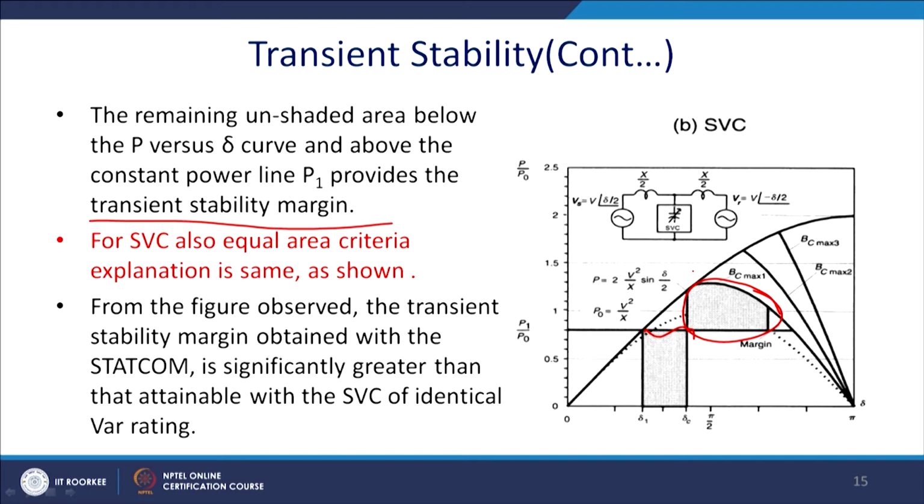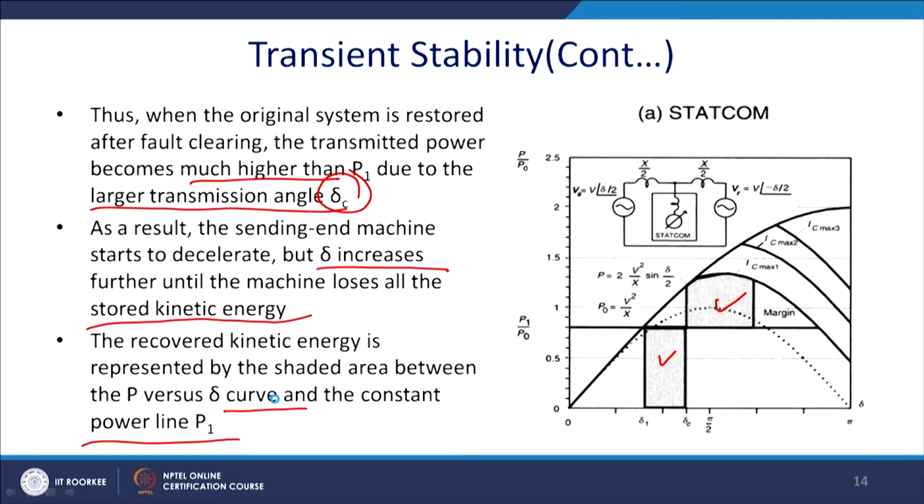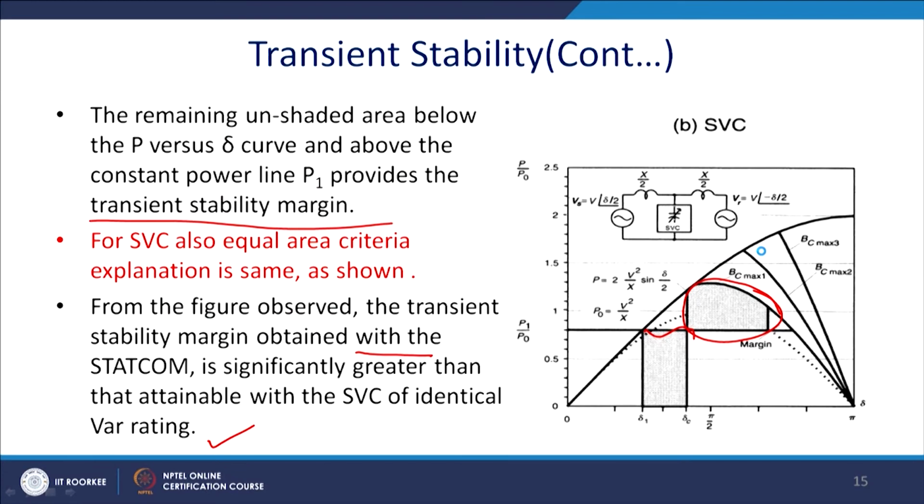From this figure, observe that the transient stability obtained with the STATCOM is significantly greater than that attainable with the SVC for the identical rating, because, please go through this figure, this is your margin and here this is your margin, since this curve is quite steep.